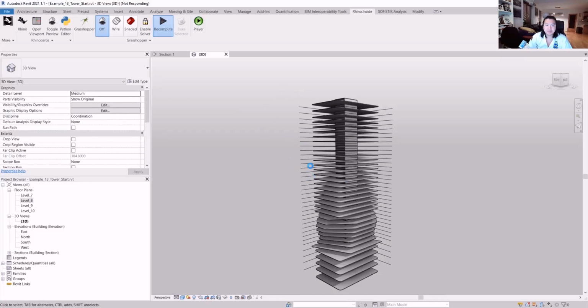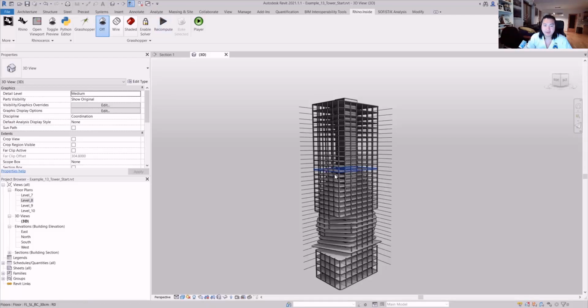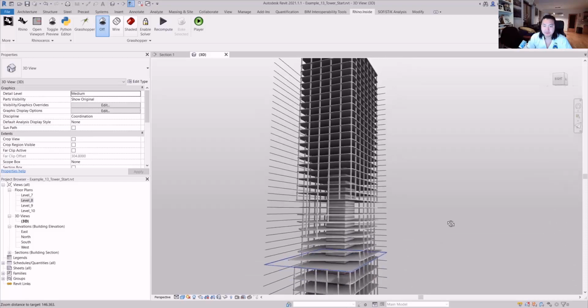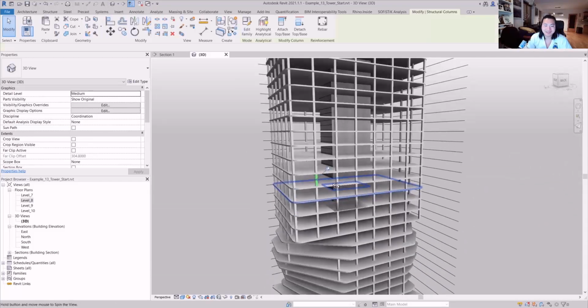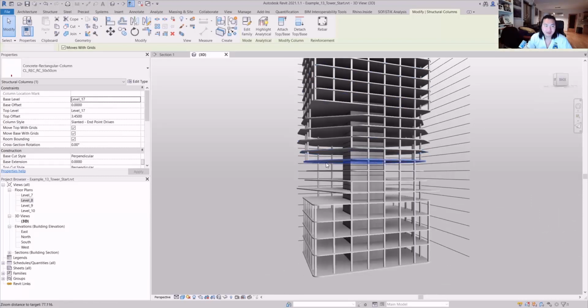Then the script only runs for the particular columns we are interested in. And Revit is just generating all the columns now from your RhinoInside script. Right, so wow, isn't it beautiful? I found it really nice. Yeah, the native column elements are there.